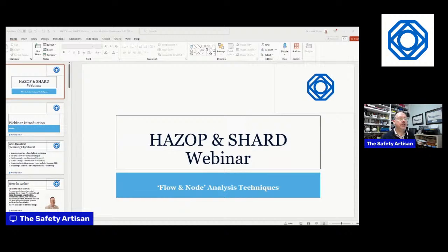So you might then choose to do a coarse HAZOP using a flow sheet and block diagram. And that's a good thing to do if you are the moderator. So if you've got to lead the HAZOP or support it, nice bit of preparation. Let's look at the system fairly coarsely in order to get an idea of what's what.